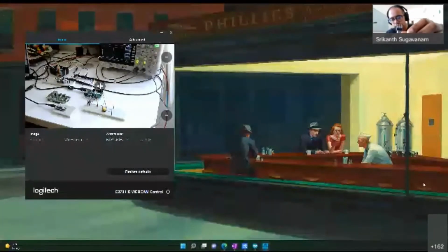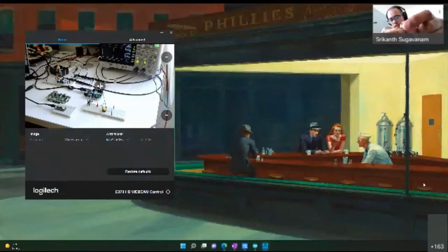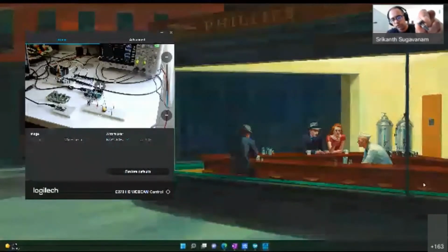What you do is you connect an input voltage on one of the legs and ground the other, and you can use it as a voltage divider between the middle and the ground pin. Now, when you turn the knob, the resistance changes, so the output voltage from the voltage divider also changes. What we are going to do is generate that voltage divider on the Arduino, where we connect one pin to 5 volts, the other pin to ground, and the middle pin to one of the analog inputs. And we'll use the Arduino to read the voltage drop across the middle pin and the ground. So that's what we are going to do.